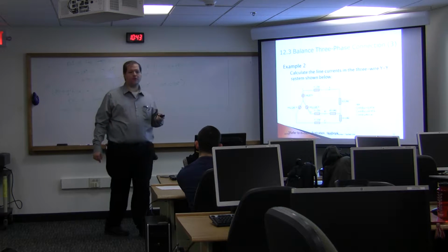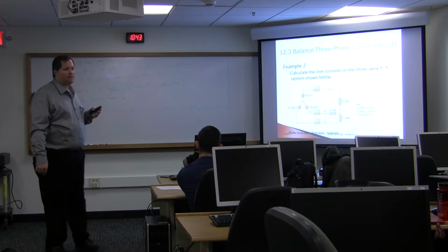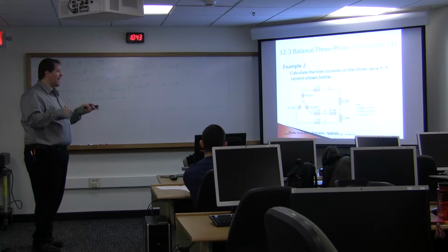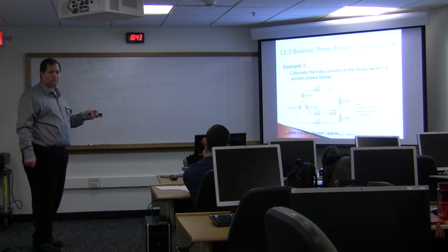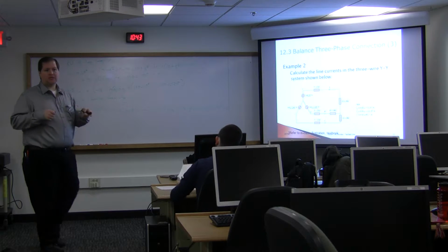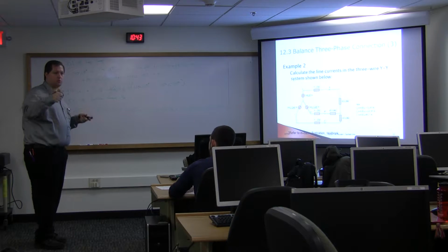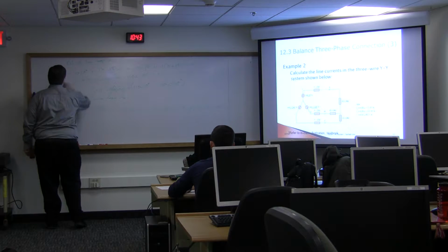And then the other thing we can measure is the line voltage. Now the line voltage is measured by measuring the voltage that you would get out of your supplies if you connected across points A and B. So if you couldn't connect to the neutral, if there wasn't actually a wire there, what voltage would you measure? So imagine I just did this as a little loop.